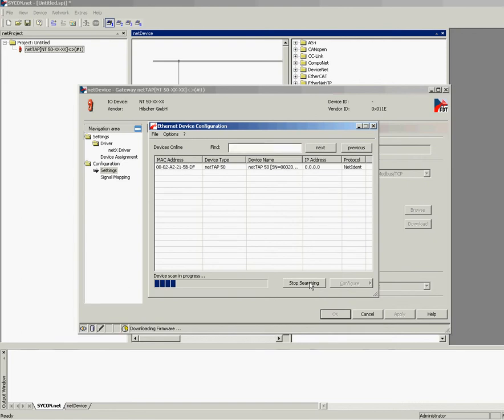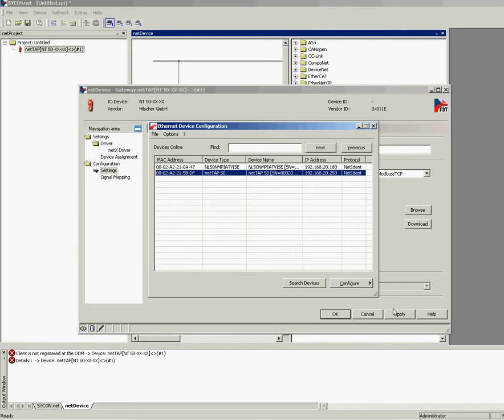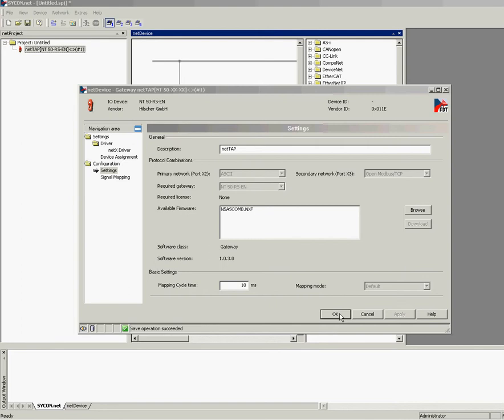Look, I make a rescan and my netTAP comes back with the IP address 0. I'm setting it now back to the correct one. Right mouse click, set IP address. Here you go. Okay, and down in the corner you see the arrow here, and Ascii.net also says it has lost the connection. Ignore that. The IP address has been set already. Again, now we are fine.